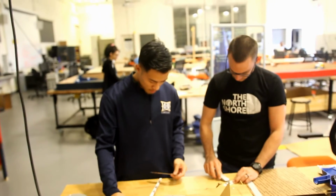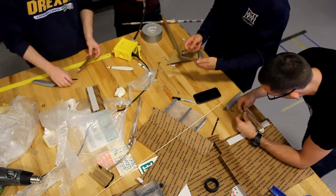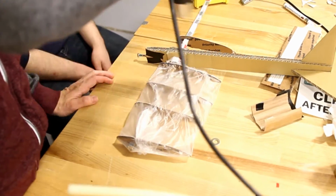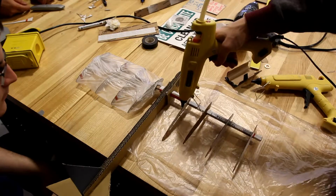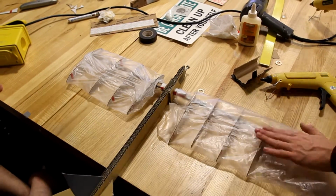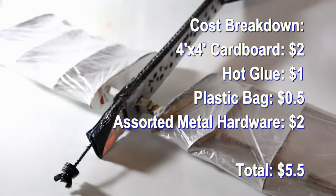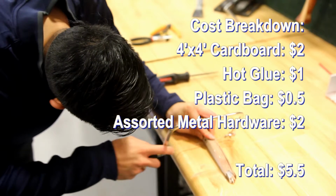Our calculations using the cardboard material provided reassurance that it would be structurally sound, as well as provide a fast means of producing multiple iterations, ensuring that the wings were covered with 2 layers of plastic and then heated so that they would conform to the rib shape. We created the skin of the wings. Additional spars were added between each rib after initial tests showed that the cardboard would bend in too far after applying that skin. The final material cost of the JunkYard jet is $5.50, given all tools such as the heat gun and box cutters are provided.